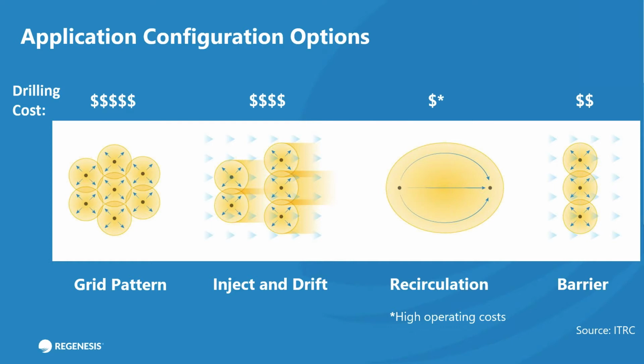Indeed, with these sites, often I find that it's a combination of barriers as a standalone technology, or barriers with grid applications where there is good delineation of that contamination in that fracture network. Indeed, the case studies that I'm going to present to you, the first 2 are case studies where we've used in situ PRBs, and the second 2 are a combination of in situ permeable reactive barriers with grid applications across known hotspots and source areas.